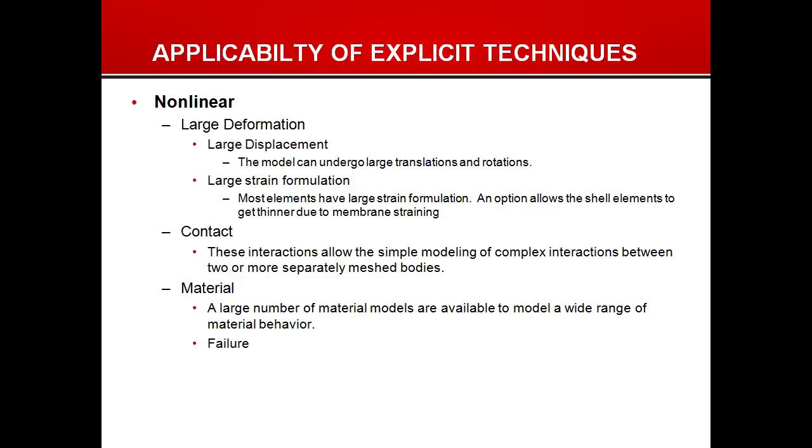Well beyond the linear elastic realm, we can deal certainly with all the standard engineering materials like aluminum, steels, titaniums, where we have an elastic plastic response. The other thing that I like to bring up when we talk about materials is that these tend to be short duration events, and we've also said that they can be large strain. We have a large strain in a short duration, and that's going to give us high strain rates. We have techniques to deal with these high strain rates.